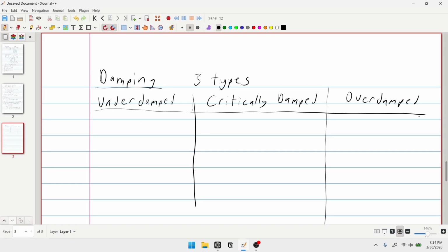And so, let's go on to when we know our circuit will be these 3, right? So, our circuit will be underdamped when alpha is less than our natural frequency, right? So back to, let me write alpha again.